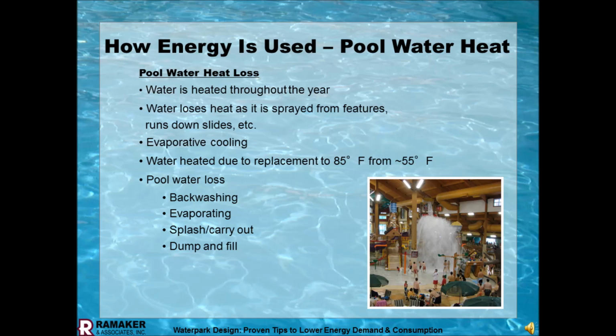The water loses heat by spraying. Or it'll lose heat just by the surface water and just evaporative cooling there. But then when you take it and spray it, or when you take it down a flume and spread it in a small sheet, or you take it in a bucket and just atomize it, you get so much evaporative cooling on it. What you're doing is adding humidity to the air, but the evaporative cooling is dropping the temperature of the water. You need to add that heat back into it.